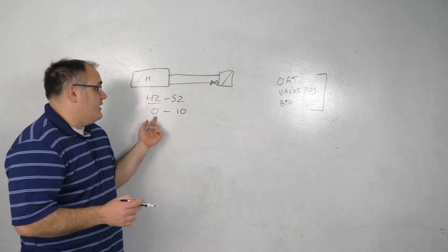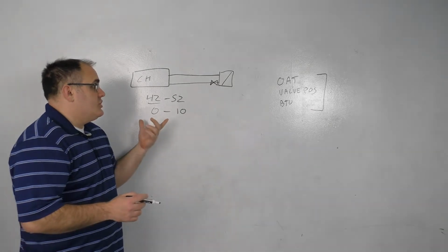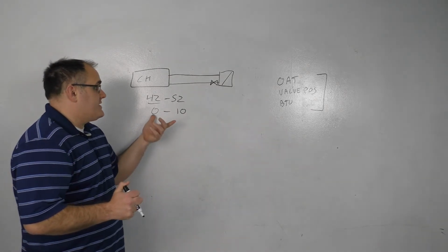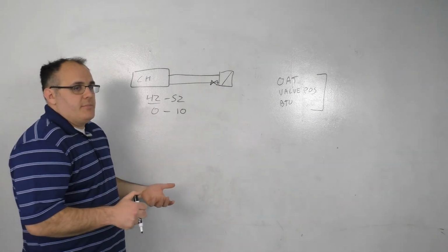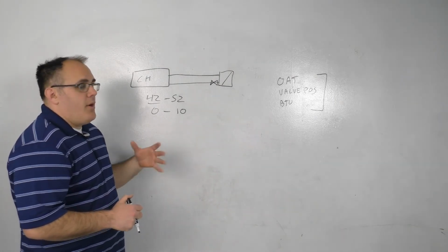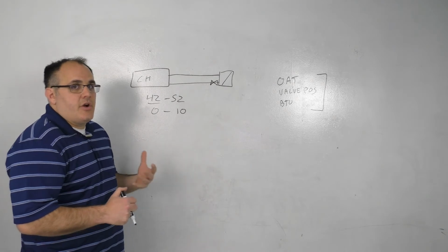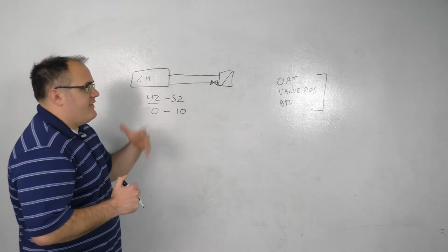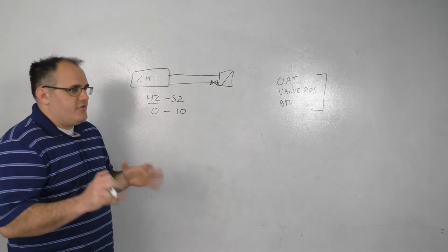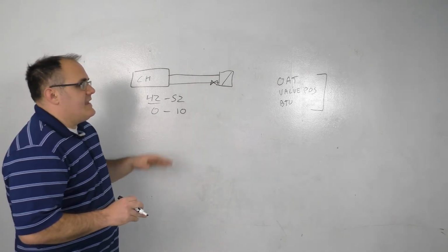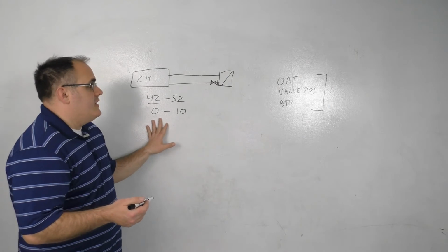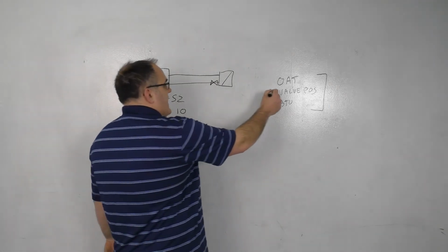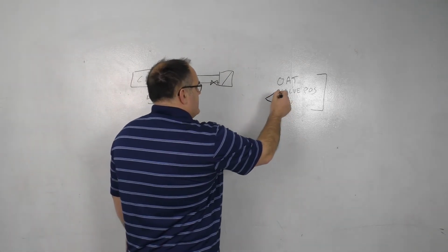It's not ideal to just sit there and keep something at 42 degrees even though there's no load in the building, because at partial load conditions the chillers aren't as efficient. Some of them are if they have variable compressors and a variety of things like that, but from a general perspective, it's better to base your reset off of one of these scenarios.